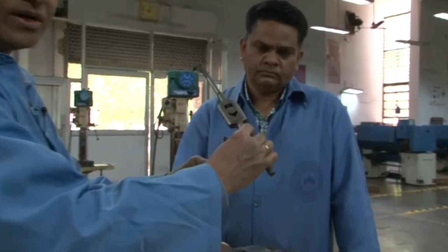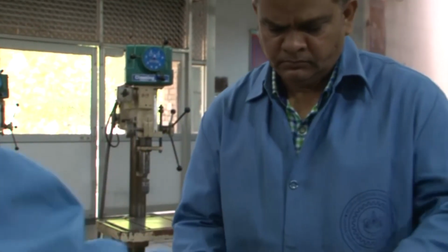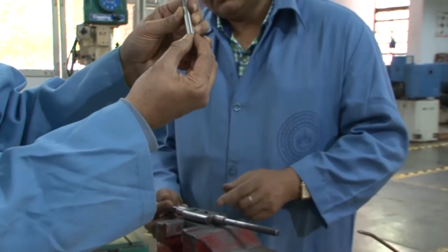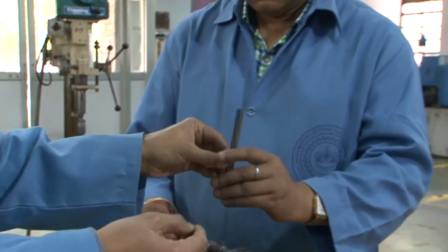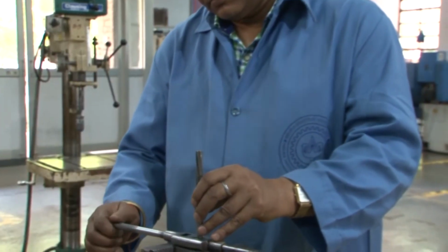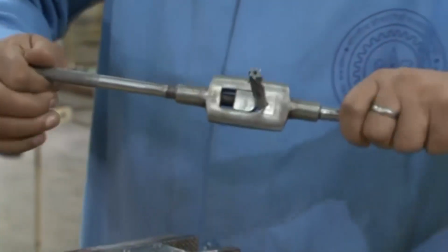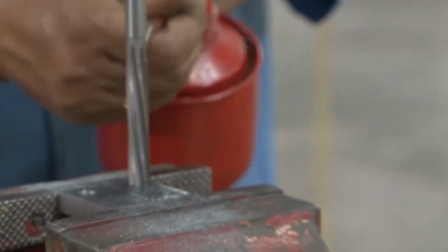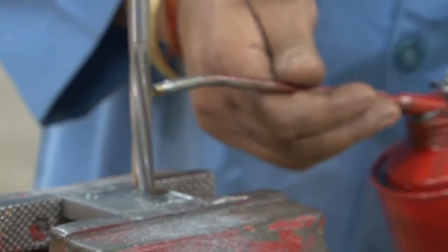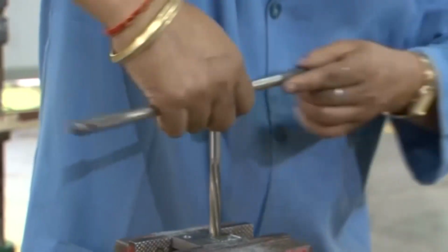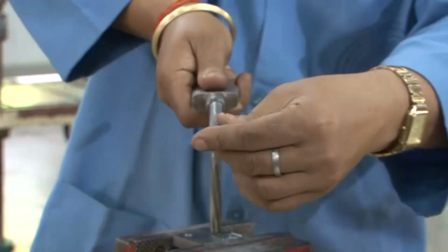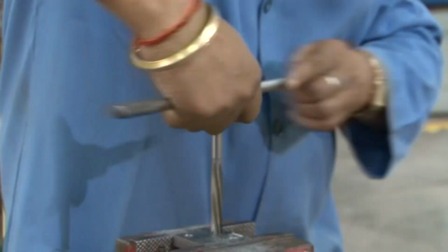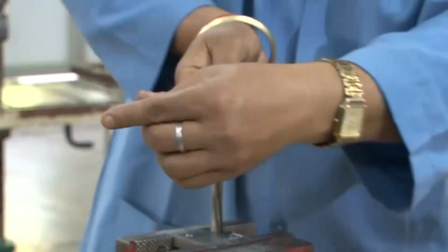Now this reamer has to be fitted in the reamer holder, using this square cross section. Now, this will be held in the reamer holder. So, this will be hand reaming. Using the hand, the force, torque as well as the thrust are given to the reamer by hand, and the hole will be reamed. That means the finish of the drilled hole will be improved, and as you have seen, a cutting fluid has been provided.